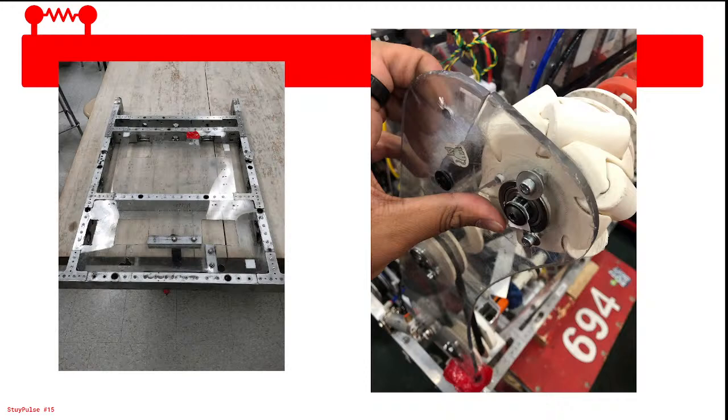So even if you do use the right thickness and stuff like that, where you place your forces matters. If we'd redesign that, we would probably change how the intake is mounted, but we would also probably make the points around the axle mounts and crossbars a little bit stronger, a little bit wider, so that there's more material.